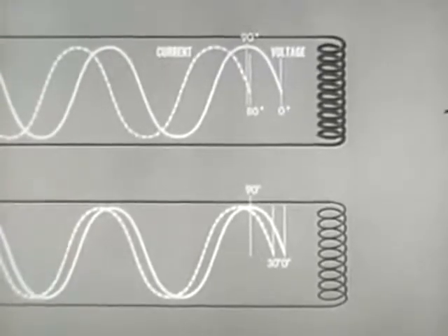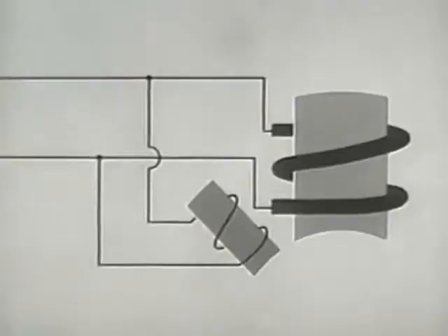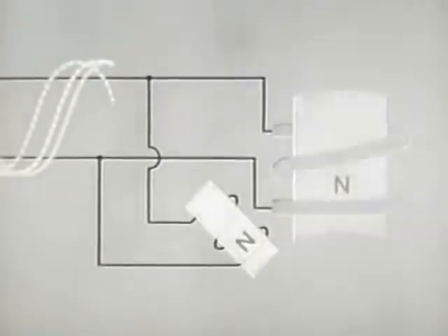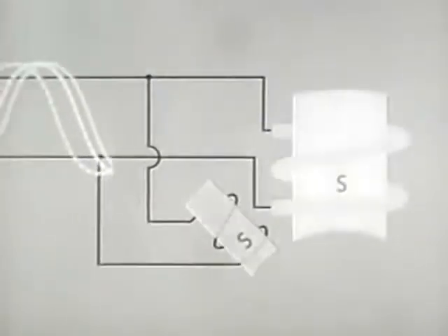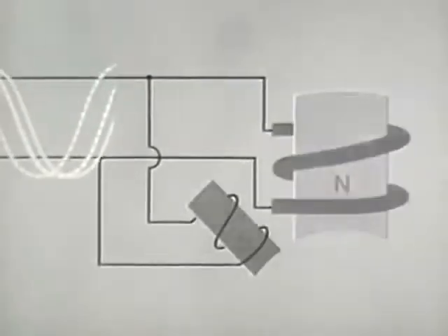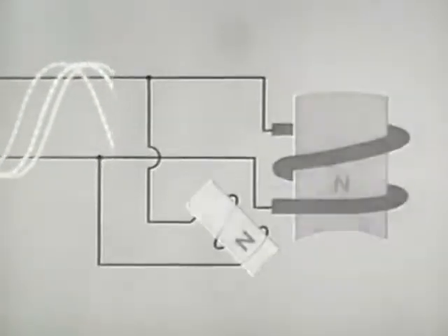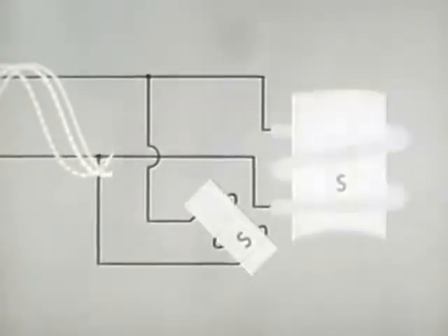The net effect is, then, that the greater resistance of the starter windings causes the phase shift to be less than that of the main winding. We now have in effect a two-phase current. The phase difference causes the starter windings to be energized before the main windings. Magnetic fields are formed progressively. This is called a split-phase motor.